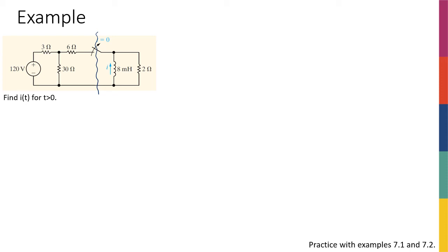The values are given and might be different from what I've seen before, but at the end of the day, it's the same circuit. So I don't even need to write all those equations to get to the decaying exponential form. I know that I, the current of the inductor, for t greater than 0, is going to be I at time 0 times e to the power of negative R over L times t.